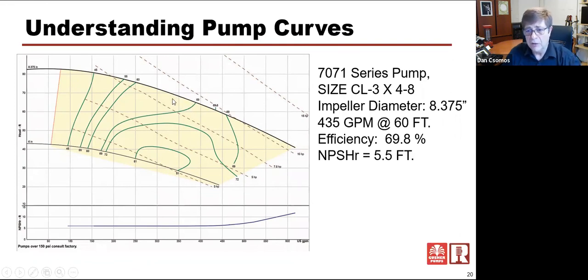And we're going to have a session that really talks about how do you calculate feet of head in a system. It got pretty lengthy trying to do it today, but basically it's friction loss and the amount of lift that you do in a system is how much resistance there is. But we're going to have a session on a little bit more advanced course than this on being able to predetermine how much resistance you're going to have in a system and determine head.